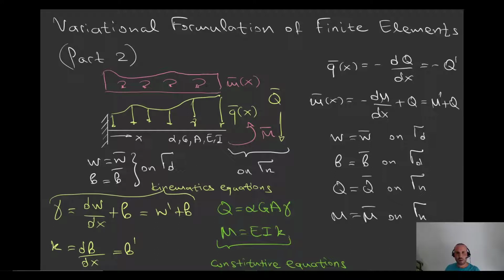In this chapter, we're going to concern ourselves with the so-called Hellinger-Reissner principle, and we will apply this principle in order to extend the variation formulation of the Timoshenko beam in order to account for the weak application of the kinematics. And let us elaborate on this.